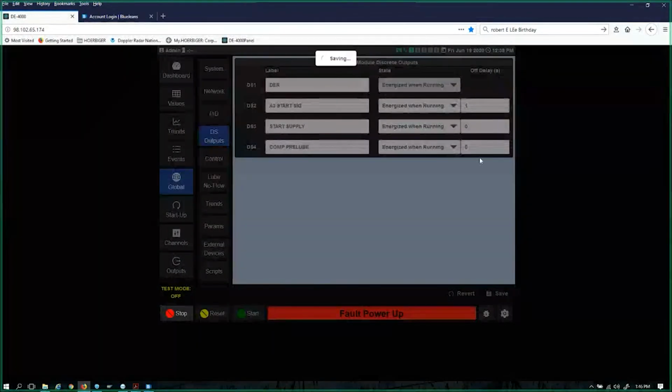Now these two are irrelevant because we're going to do something slightly different with them, but we're going to leave them at 0 on this page. Now, for these effects to take change, same as the RPM, I may require a power cycle. You can see in the background, look past this saving point that's locked up on me, you can see these up and down arrows. And that's exactly what's happened. Because I made so many changes on this page, the system's requiring me to do a power cycle. So I will go and do that right now.